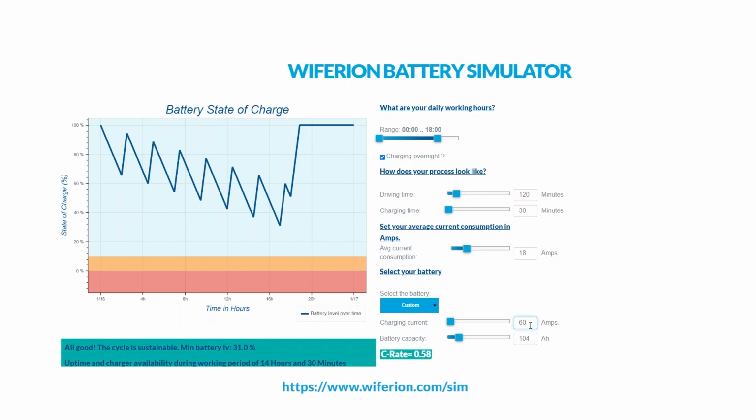Do you need 60 or 200 amps of charging? Do you need a 100 AH battery or a 400 AH battery? Those are the questions you need to answer very early in your design process, and those are the questions you can answer with our simulator.